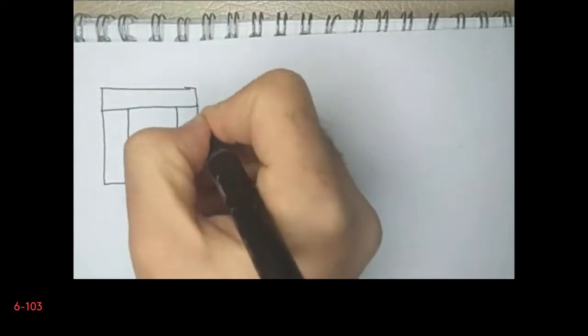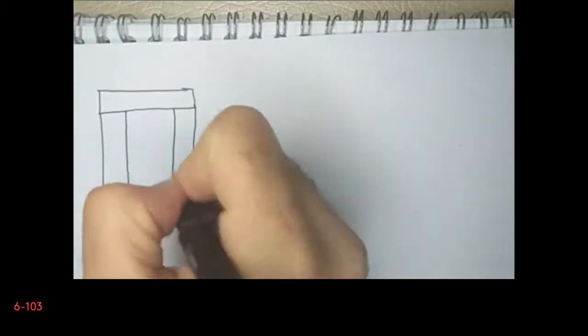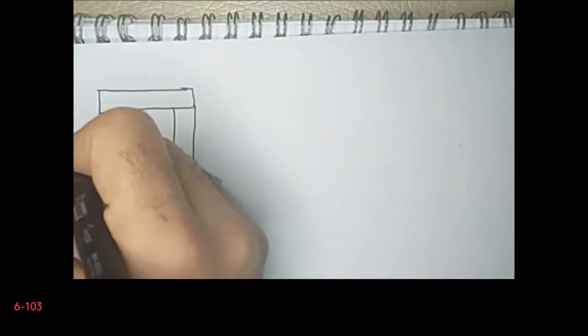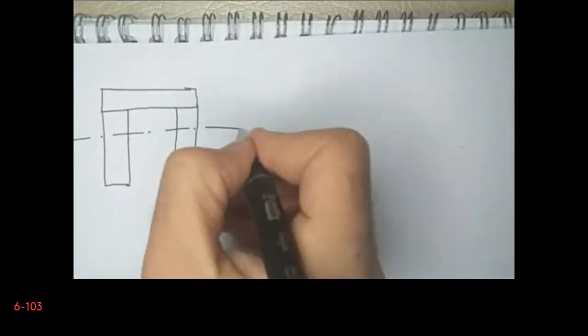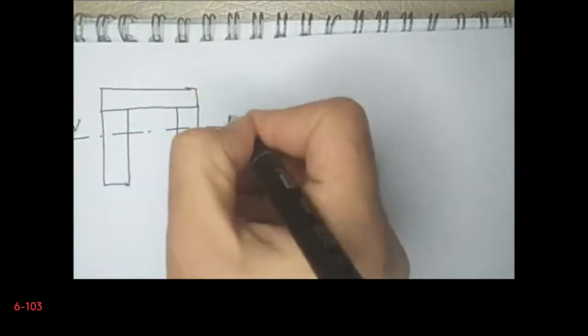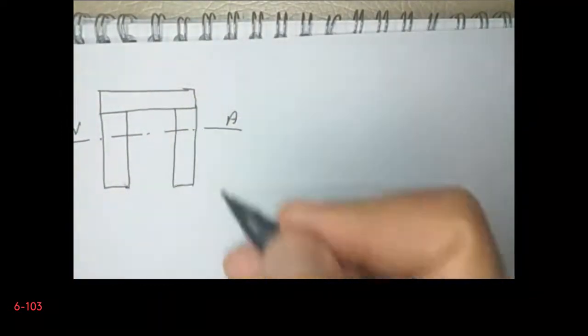And certainly we have the neutral axis somewhere. We don't know the location of the neutral axis. So the first thing that we need to do is to determine or calculate the location of the neutral axis. As a result, we will calculate the centroid. I need a reference point. In fact, I prefer to choose the bottom of the cross section as my reference.